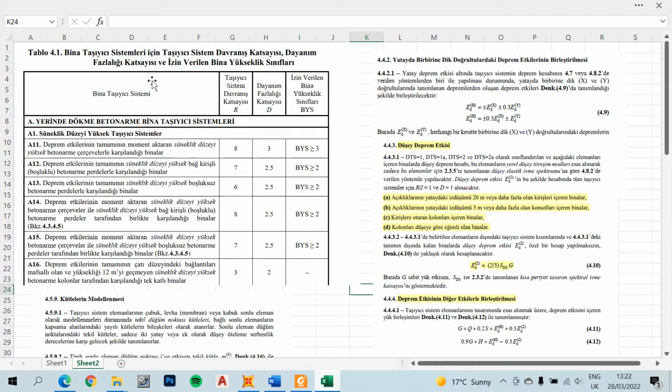The engineers suggest that if your building is going to be ductile, it is allowable to use an R factor, because the total seismic load is divided by the R factor to get the actual earthquake load that you apply to the building. So it is also called a reduction factor, because they allow you to use smaller earthquake loads, assuming that your building will be more ductile, so it will deform. And if it deforms, it can sustain lateral forces without losing too much of its strength.